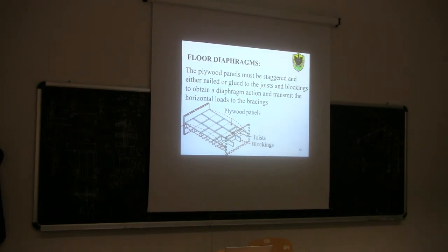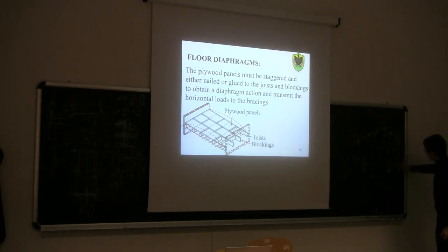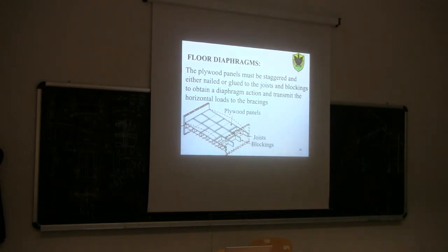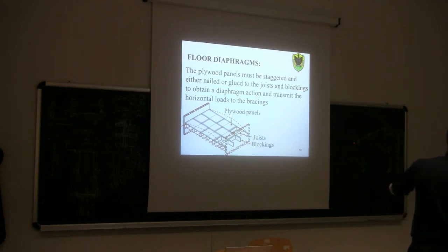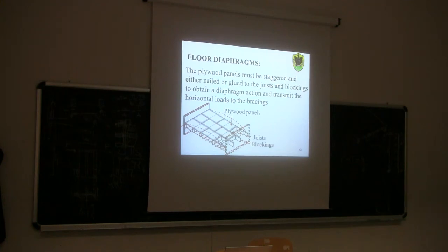Conservative. And then the shear, who is going to resist the shear? In a cross-section like this, like before, mostly I would say the web. Again, strictly speaking, we have a parabolic distribution. But this parabolic distribution is very close to a uniformly distributed one. Because if you look at the curvature of the parabola, it's not very important. So again, we can assume that all the sheathing is going to carry the shear force.